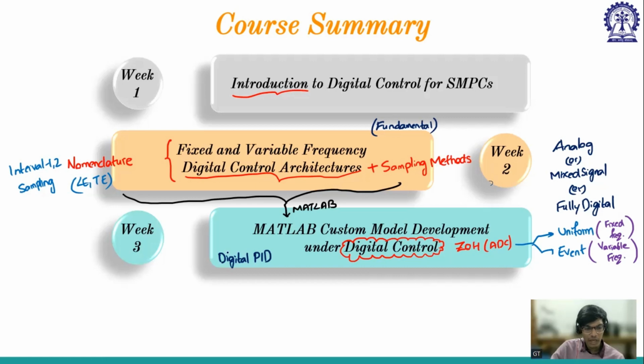According to the time period of the switching frequency, it will keep on updating. So it could update multiple times in a switching cycle, or once for multiple cycles, which again we don't want. We want it to be updated once in a cycle. So for variable frequency, our PID controller should be event triggered. But the block already available in MATLAB is not event triggered. It will be triggered by the frequency clock that we have to enter.